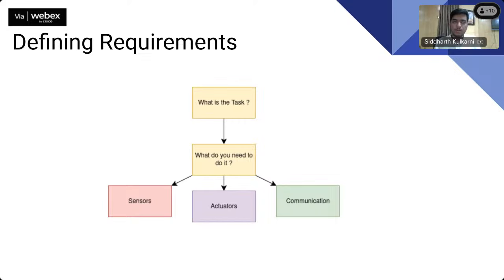What a soil moisture sensor will do is tell you the moisture of the soil. So why do you need a soil moisture sensor? That is the first question. What is the task that you need it for? It could be to detect whether the soil is dry or wet, or whether it is time to give water, or to detect some other phenomenon, maybe the light intensity, temperature, humidity, or the NPK values, that is, mineral contents of the soil. Typically, according to this application, the use case changes. So you cannot just use a soil moisture sensor to do indirect measurements, like assuming that if my soil is dry, the temperature is high or low. This kind of indirect measurement does not give you the right answer.